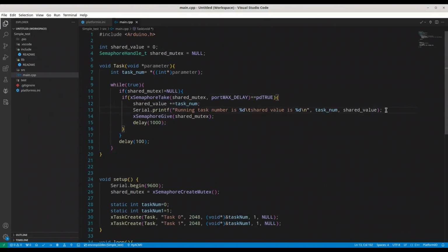So this in front of you is code from our previous episode. There I showed you how to use multi-threading on ESP32 microcontroller, where two tasks are sharing a common variable by using semaphore handle. And today we are going to continue with the subject of multi-threading. We are going to use this code, but we are going to modify it. And I'm going to show you how to share serial communication between two tasks.